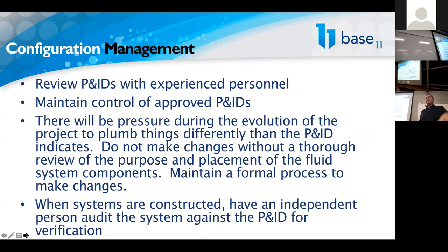So I talked about having a formal process to change your system design, to make sure that you put as much effort into reviewing any changes as you do into the design in the first place. Once you have assembled your system, we have found it to be extremely helpful to have someone that's knowledgeable of fluid systems take your plumbing and instrumentation diagram and audit your system to make certain that what was built is actually what you designed.